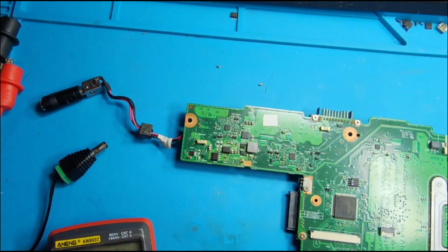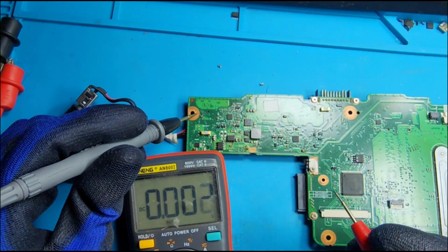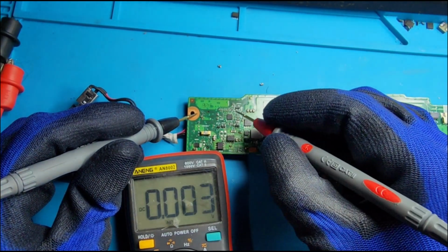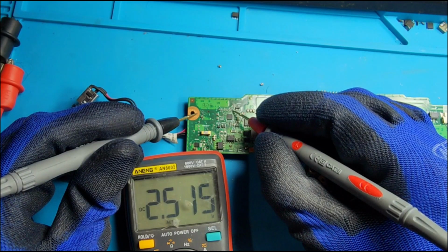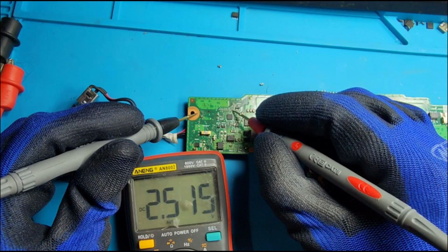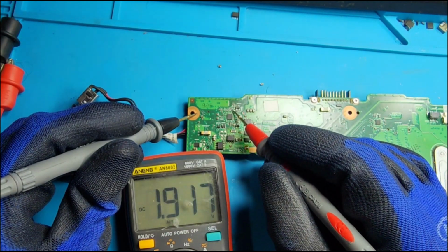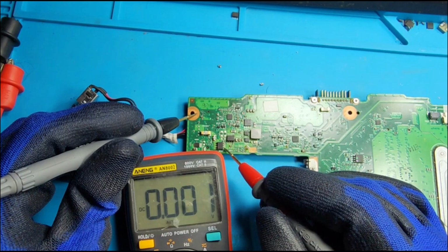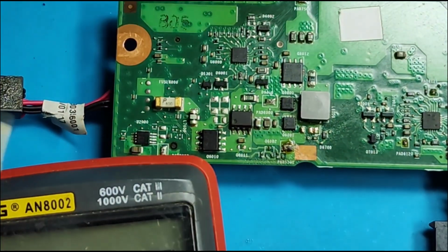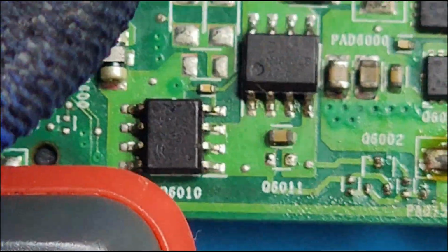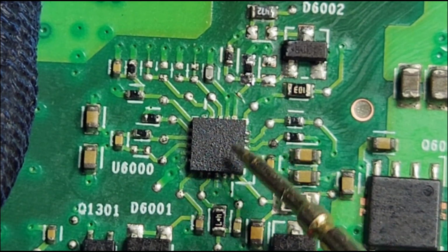So now let me connect the adapter and check the voltage on the resistor divider. So if I check the voltage, yes, now we have 2.5 volt. So approximately okay. So 0.1 volt is higher than the expected voltage. So what we have to do now, we may not have the voltage because we have now already cut the line. So we have to jumper that line together, this line here, and see whether we have the main power rail. Okay.